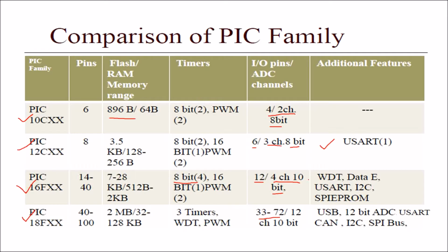In PIC16F, watchdog timer, then E port is included, USART block is available, I2C block is available, SPI protocol is available, E2PROM is also included. For 18F version, USB is available, 12-bit ADC is available, USART, CAN protocol, I2C and SPI protocols are available.